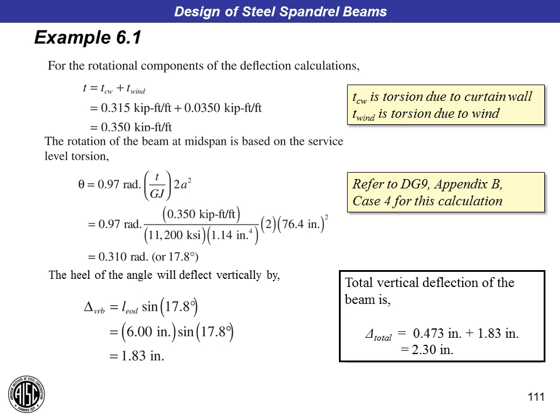In my practice, I almost always break up the span with roll beams. I don't use kickers all that often, though, particularly on roof decks, where I might be trying to put the upper end of the kicker into roof deck, which doesn't have much capacity. I almost always use roll beams, and I do it for a couple of reasons. One, because I need to restrain the torsional rotation, but two, because it laterally braces the bottom flange of the spandrel beam against lateral torsional buckling, which you might experience in a wind uplift case.